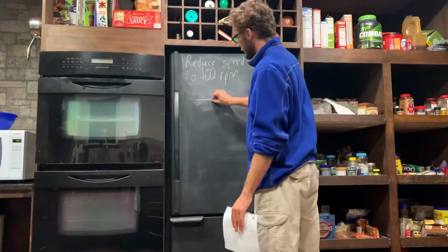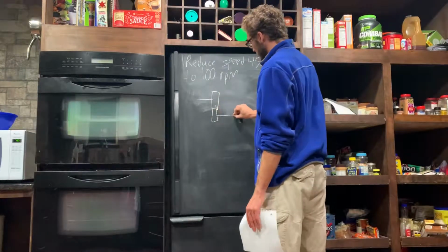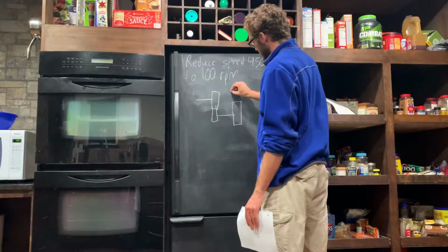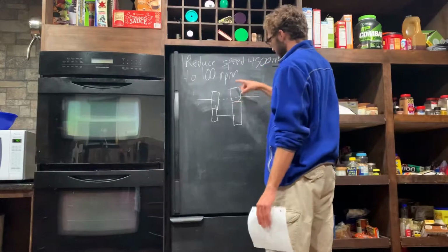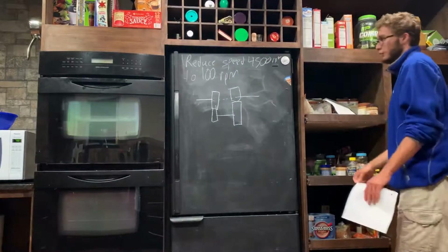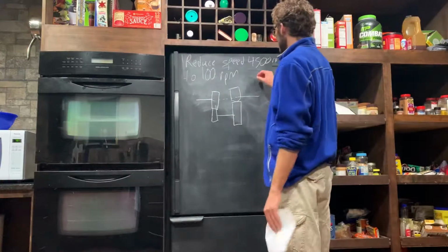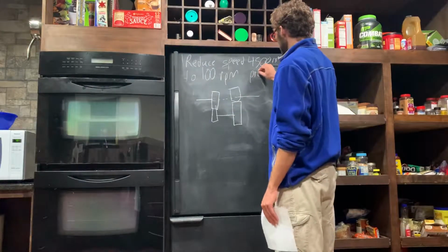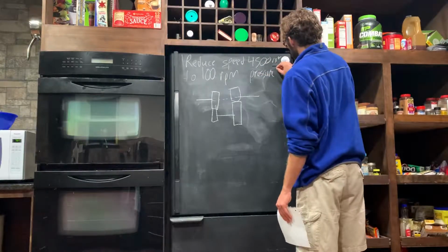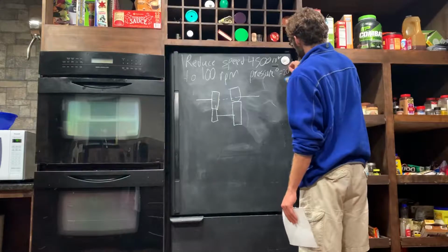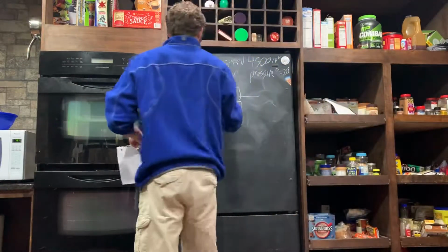So we're going to have an input shaft here, some gear, some other gear, an output shaft, a gear, and that should line up perfectly. We're also going to have a pressure angle of 20 degrees, because we need to use our tables to ensure we have no interference. So those are the requirements.